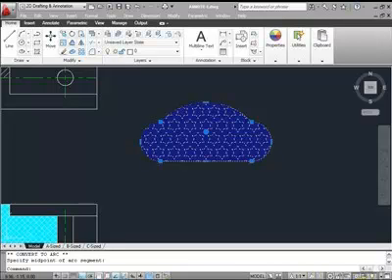Just a note about the transparency that we just used earlier with some of these hatches. All objects in the AutoCAD 2011 package now have the ability to hold transparency. So you can set transparency for all objects, not just hatches. And transparency can be plotted, but just so that you all know, as a default when it ships in AutoCAD, transparency is set to not plot.